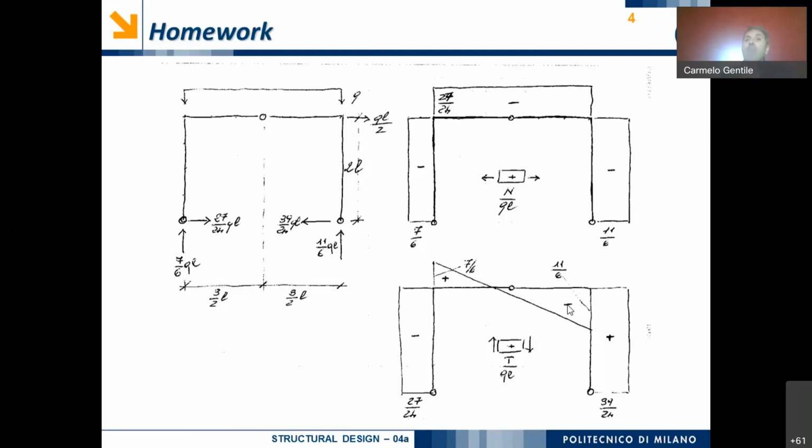Before moving to bending moment, let's see what we expect in terms of bending moment for the two columns. First of all, we expect that bending moment corresponding to the hinges is equal to 0. Afterwards, when we are moving along the column and we are making cuts at an increasing distance from the ground hinge, the distance of this force from this cut is increasing.